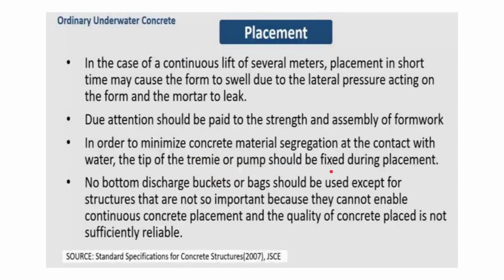Okay, during placement it should be fixed. No bottom discharge buckets or bags should be used except for structures that are not so important, because they cannot enable continuous concrete placement, and the quality of concrete placed is not sufficiently reliable, because that is a very approximate method. Okay, very, very old method, very inefficient method.